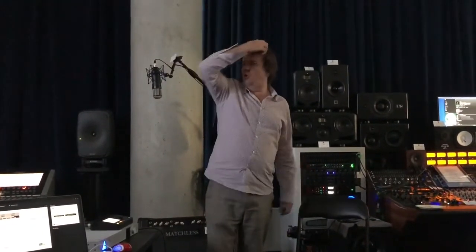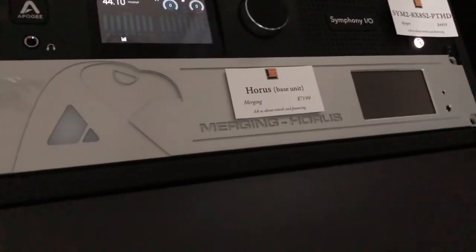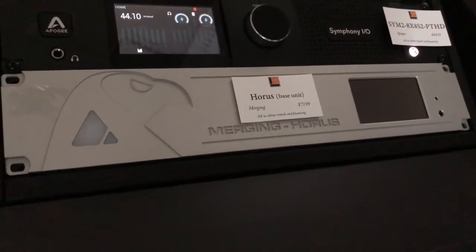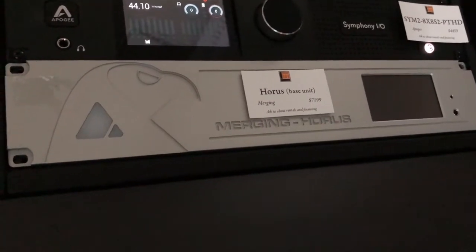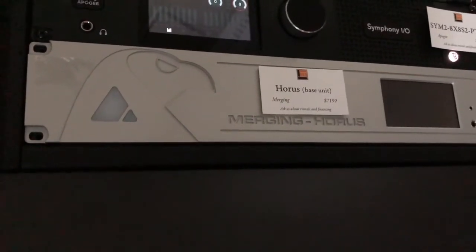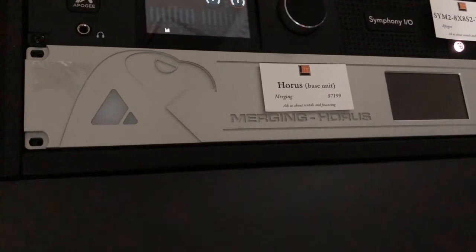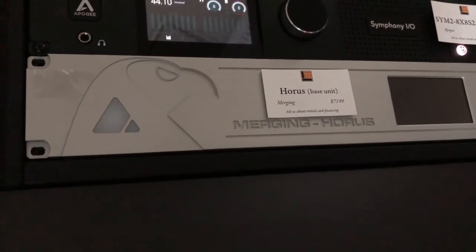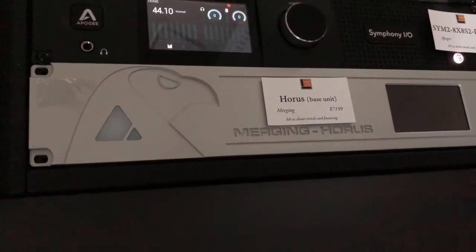Coming a little bit into Horus and Hapi, these are our traditional converters. On the left side, this is the Horus. On the right side is the Hapi. On the left side these are 2 units with a touchscreen on the front, and this is the back picture. This back picture has, to explain quickly, at the bottom all the digital inputs and outputs: 24 AES/EBU, 64 MADI optic and coaxial, extendable to 128. And on the left side, you have the word clock input if needed, and breakout cable for LTC, MIDI, and so on.